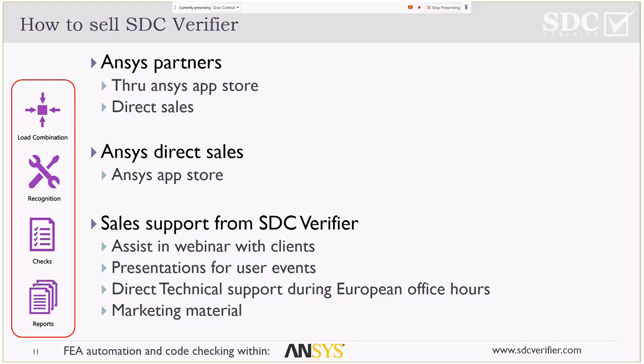You need to isolate the part where you want to do detailed analysis, export the geometry, export the loads, import all that in Ansys, do the calculation, do the nonlinear stuff, and then it is very hard to get the nonlinear or detailed Ansys analysis back into the global code-based program. So it is a very tedious design